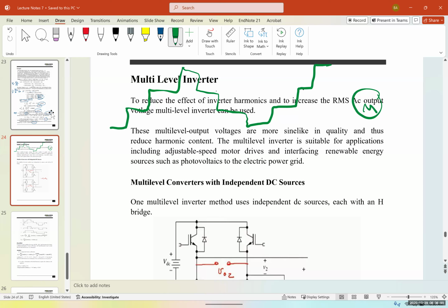If the inverter looks like this, the motor is going to run. You may damage the motor after a few months or a year if it's a bad inverter, but the cost is just the wiring of a motor, and probably the first thing that blows up is the compensation capacitors.